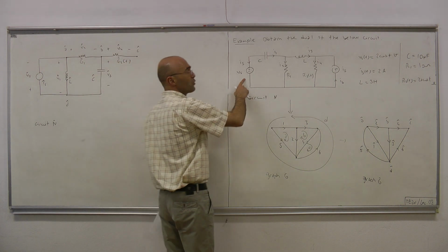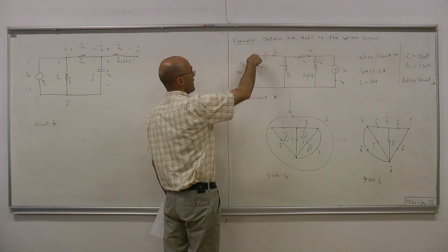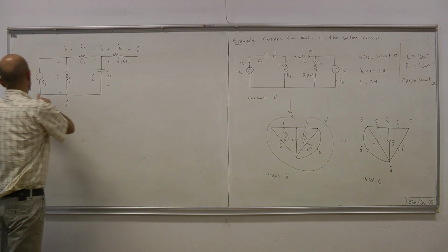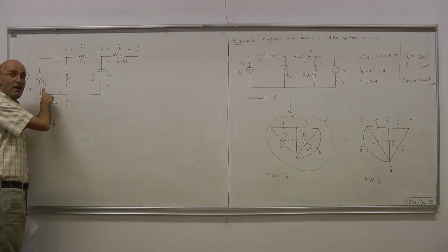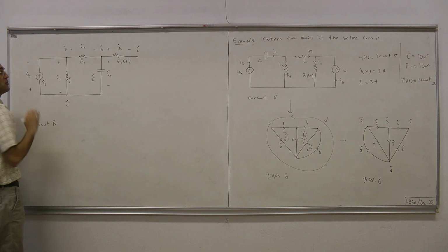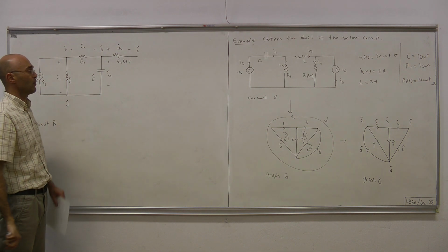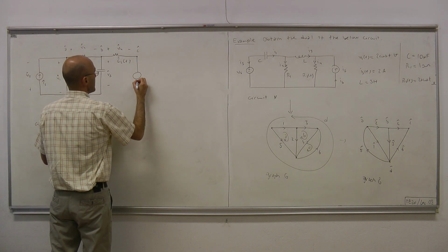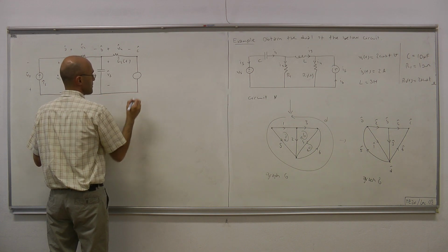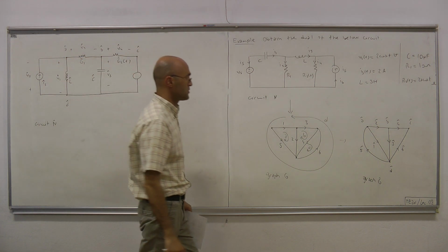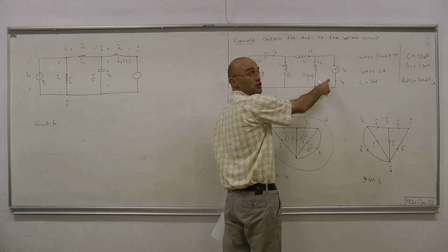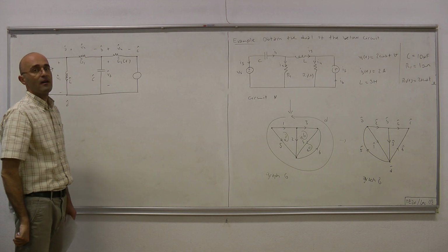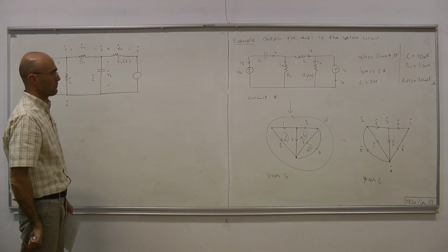For that, you get the original circuit. In the original circuit here, this current and this polarity obeys passive sign convention. Here, this voltage and this current must also obey passive sign convention, meaning that this is the direction of the current of the current source. And finally, what remains is another source here, the last source, that corresponds to branch number 6. Here we have branch number 6, the original circuit is a current source, therefore in the dual circuit it should be a voltage source. Okay.